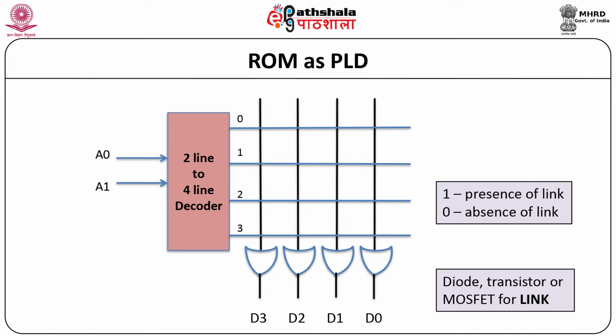For each binary address input pattern, exactly one of the horizontal lines of the address decoder is produced. In the example, a 2 to 4 line decoder is required to control 4 word lines or rows corresponding to 4 memory addresses. Basically, the decoder provides the product terms.